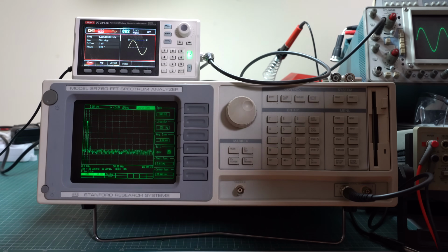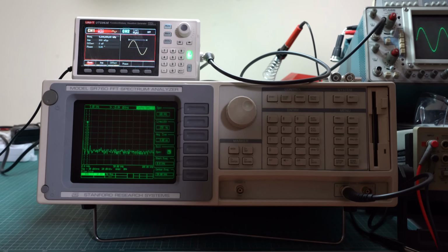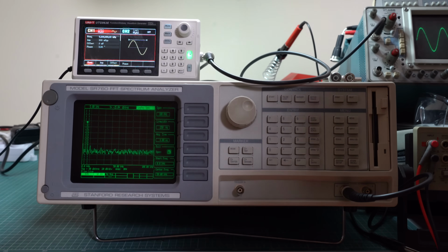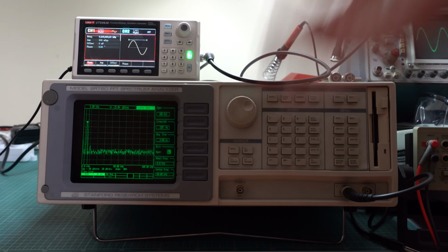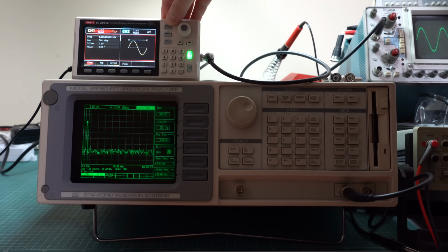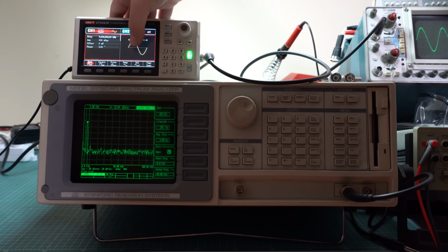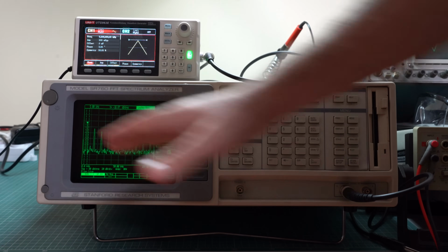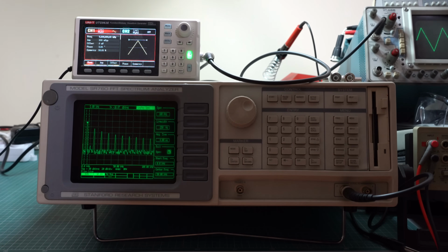First of all, a spectrum analyzer can be used for RF transmitter testing. So it's very important when running a transmitter that the signal is clean before putting it into an antenna, because the transmitter needs to comply with local regulations, and you have to make sure that the transmitter doesn't interfere with anything else. So if your signal looks like this, it's probably clean enough to be put into an antenna. However, if you have some sort of horrible distortion somewhere in the signal path, your signal could look something like this, and this means that you have lots of harmonics to take care of and to get rid of before putting the signal into an antenna in a safe manner.